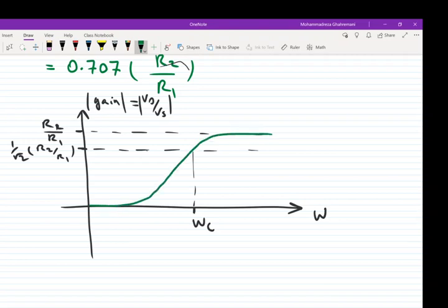Yeah, it's better. So this one is the frequency response of this filter. And as you see, what's the difference between this filter and the passive high pass filter that we saw in the previous lecture? It's big. In the previous lecture we knew that the gain is less than 1, but here the gain is R2 over R1, and it can be any value.